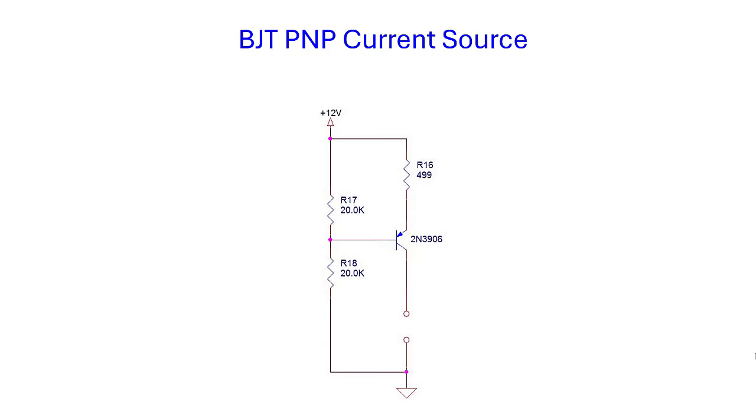The current that flows through the emitter will be constant and equal to 1 plus beta times the base current, IB. Beta times IB will flow through any output load resistance that is connected to the collector, regardless of the value. The limitation is the overhead voltage on the load. The constant current will saturate once the 12-volt supply limitation is reached.